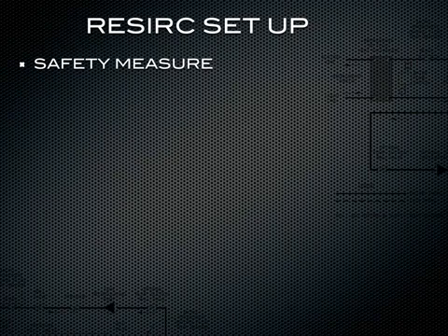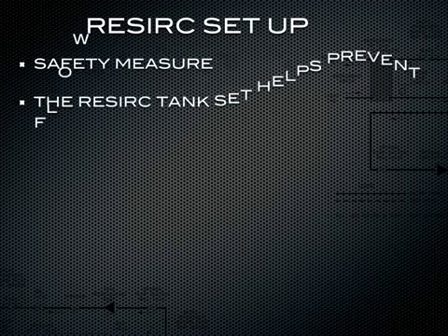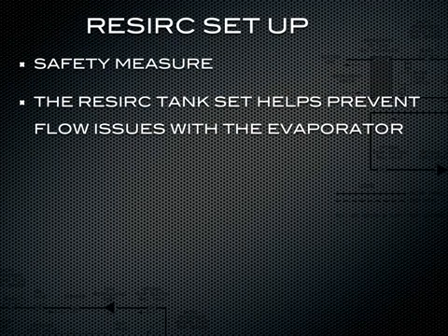On a recirc tank setup, we have 2 separate loops. The recirc pump will service that evaporator and keep your desired tank temperature, and the system pump will always pull that cold water off the tank back out to your process to cool it. So anything external to the chiller will not affect the chiller refrigeration system.